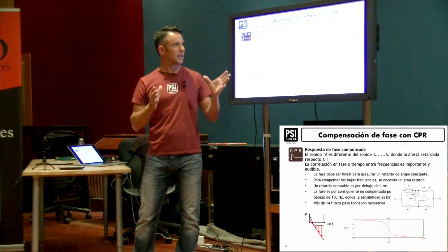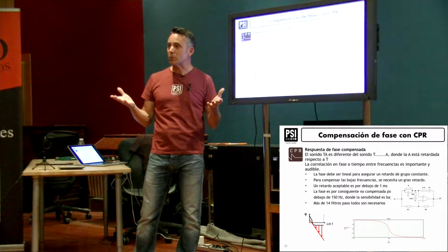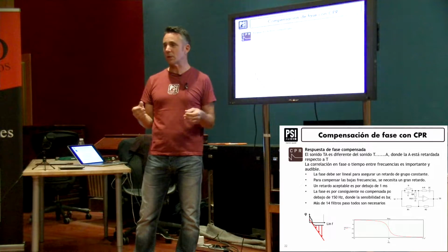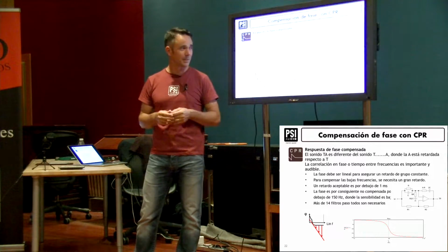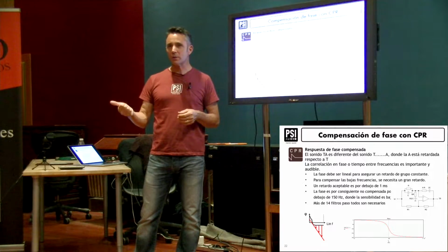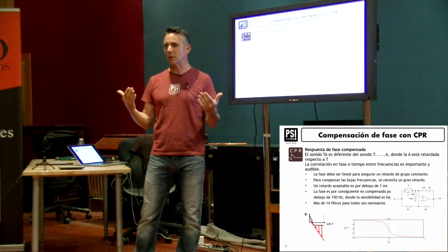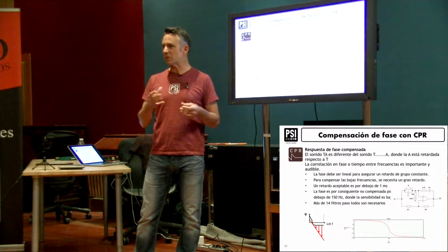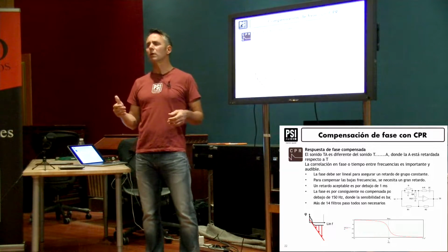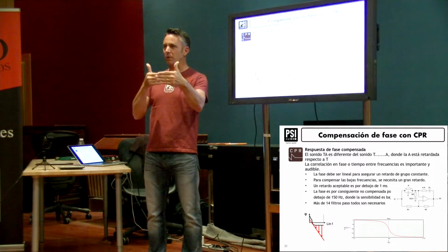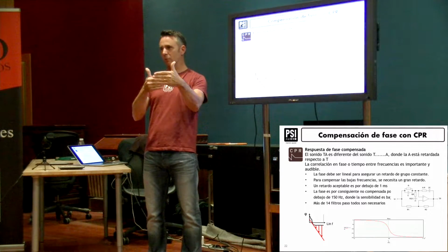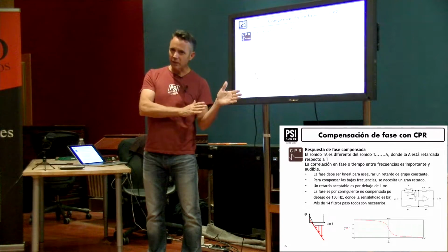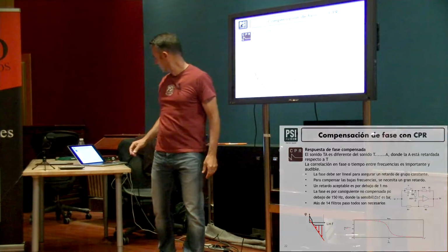Latency in the system is not a problem when you're listening to music. You press play, you can wait for 3-4 seconds until the music comes out. It's not a problem as long as it's all coming out at the same time. But when you're recording, mixing, or doing post-production, you can't have too much delay, and normally it's recognized that 1 millisecond is the maximum latency you want in your loudspeaker. 1 millisecond is again approximately 35 centimeters, moving back or forward, so it's not that much. But we've limited ourselves to half a millisecond, and we can correct the phase here down to 150 hertz.